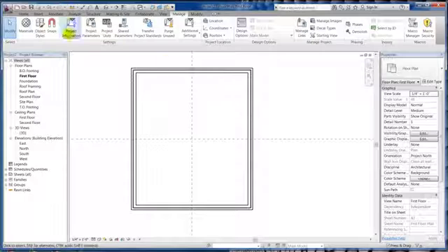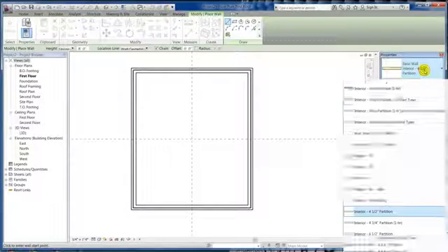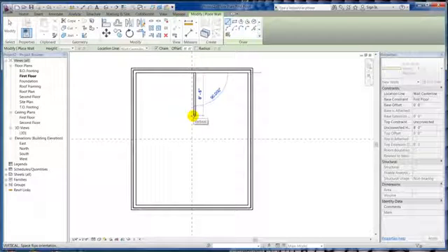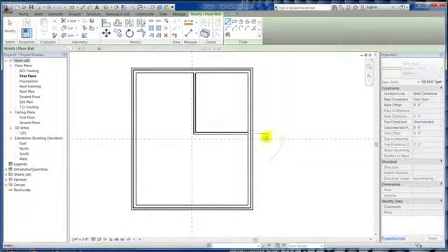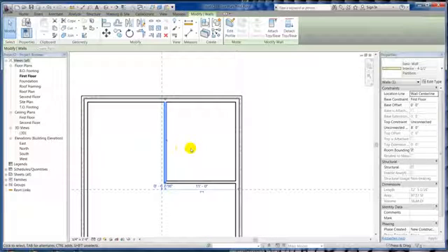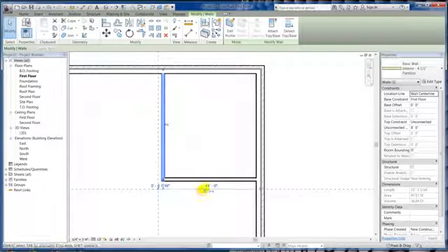So yes, interior walls, we can go back into the wall command, do my 4.5 inch partition walls. And I usually just kind of eyeball quick, pretty close. We'll do 11 by 11 foot 6 because I've got my temporary dimensions, so I can still, that's right on the line, so it's hard to see, but that's 11 foot.